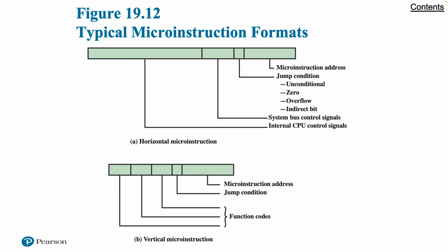So we could construct a control word in which each bit represents one control line. Then each microoperation would be represented by a different pattern of ones and zeros in the control word. Suppose we string together a sequence of control words to represent the sequence of microoperations performed by the control unit. Next, we must recognize that the sequence of microoperations is not fixed. Sometimes we have an indirect cycle, sometimes we do not.